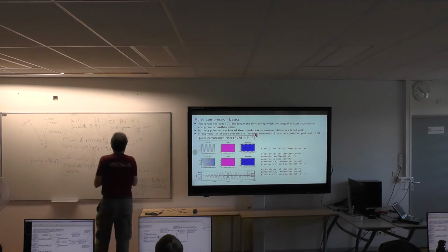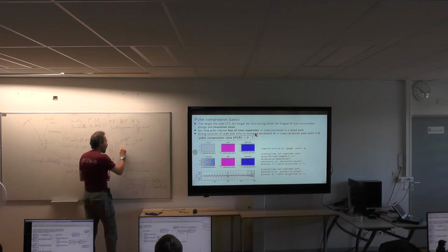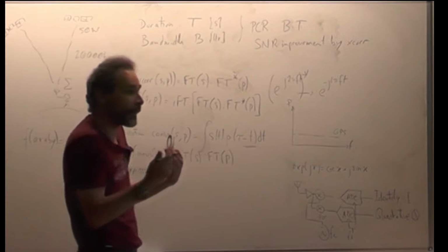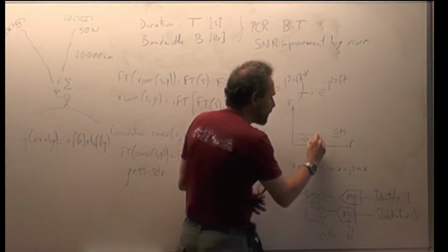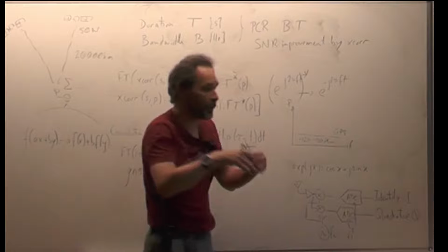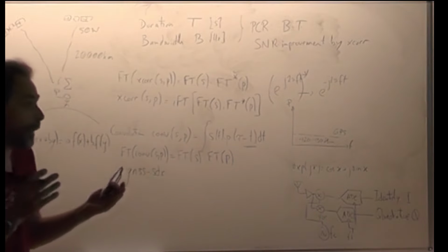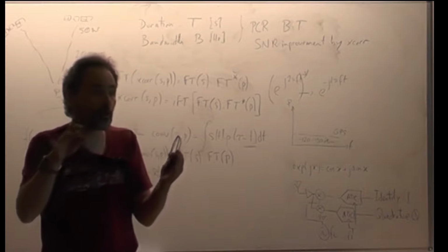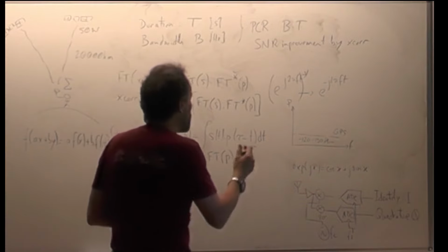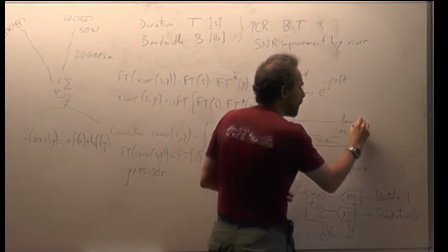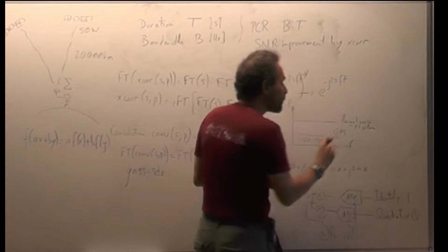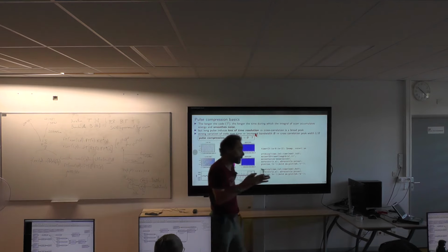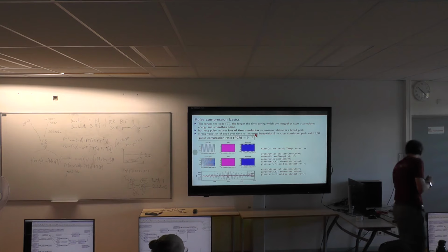So if I look at what this means, you might get in power a GPS signal. So your GPS signal, well, when you look at the standards, it should be at least minus 130 dBm. So it's going to be something like minus 120, minus 130 dBm, depending where you're in this free space or in the canopy. And what you can demonstrate is that over the 2 megahertz bandwidth of your GPS signal, the thermal noise integrated over 2 megahertz is minus 174 dBm per hertz multiplied by the 2 megahertz bandwidth, which is going to be something like minus 111 dBm. So you see that your GPS is 10 to 20 dB below thermal noise. If you look at the spectrum of a GPS signal, you're not going to see it. It's just a slight bump above the background.